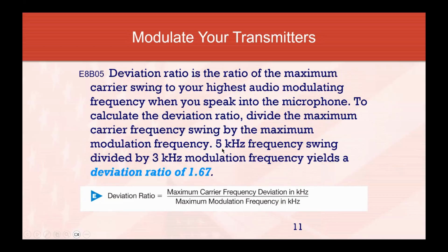They have one here where they have a 5 kilohertz frequency swing and a 3 kilohertz modulating frequency. 5 divided by 3 is 1.67.